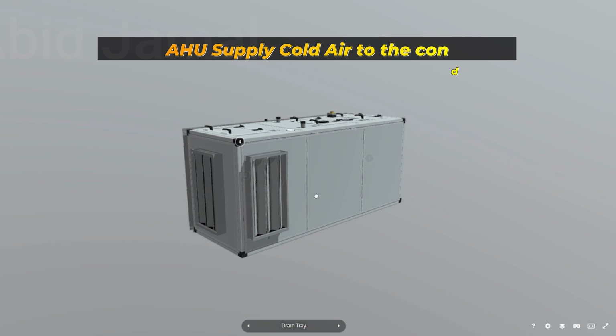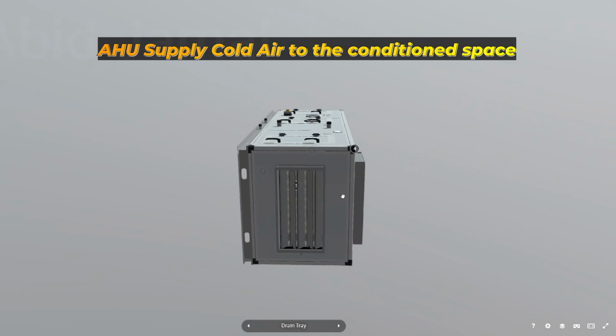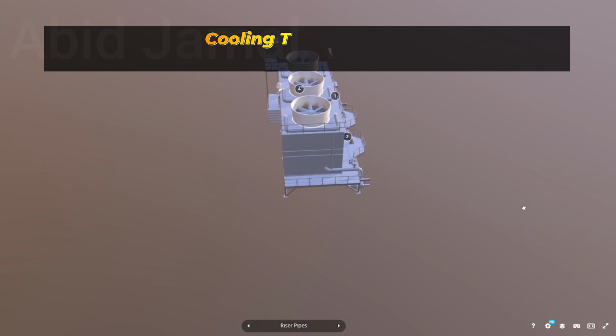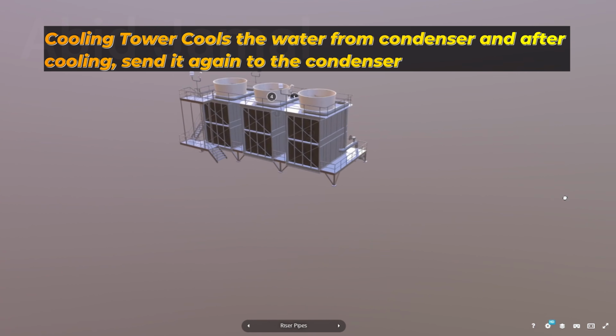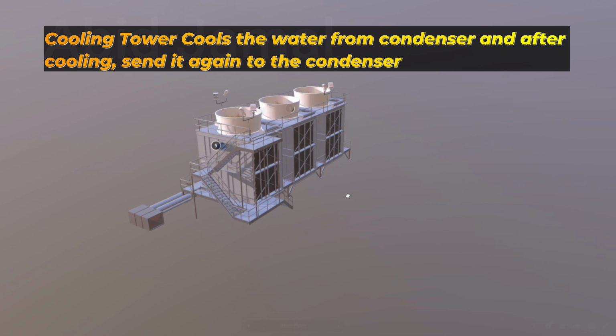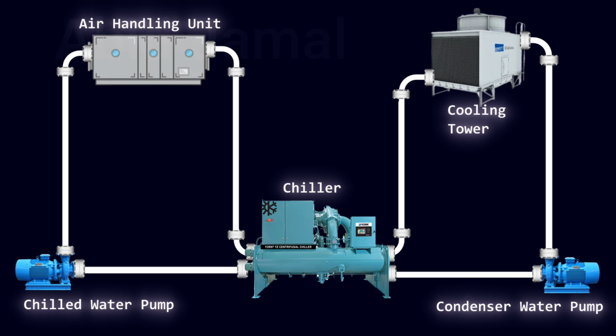The function of the system is to use the water from the chiller's evaporator to supply cool air properly into the room. The cooling tower reduces the temperature of the water coming from the condenser and sends it back to the condenser. Now let's look at the basic working process.